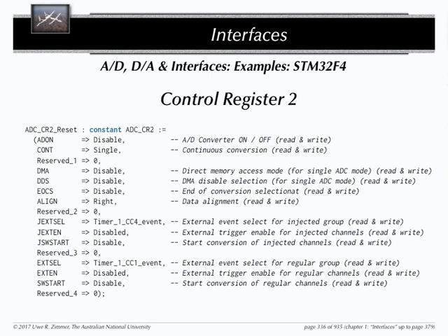Why is that? Well, I usually want to read it and change something and write back. So what do you do if you want to change 5 things at the same time? What do you do if you say you want to change 2 things at the same time? You can, of course, just use the actual hardware mapped variable and write to this record entry, write to this record entry, write to this record entry. But that means that every time you touch that, your compiler will write this out immediately. That may bring atomicity problems with it.